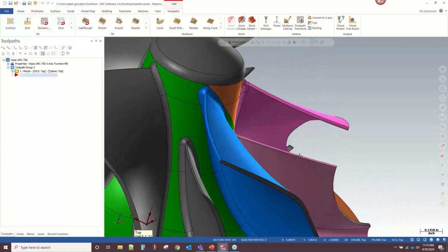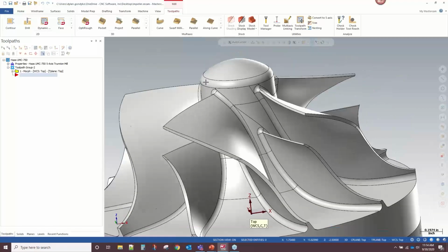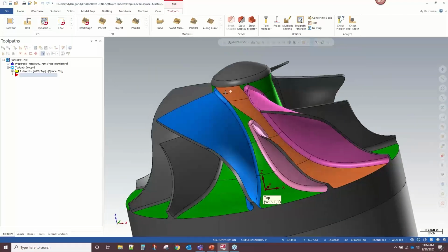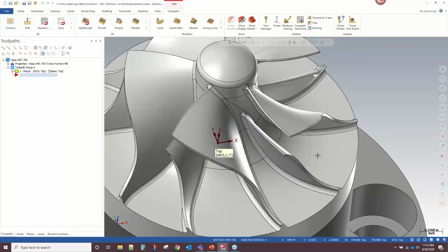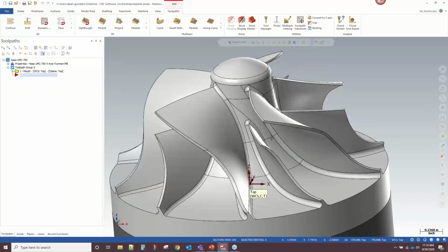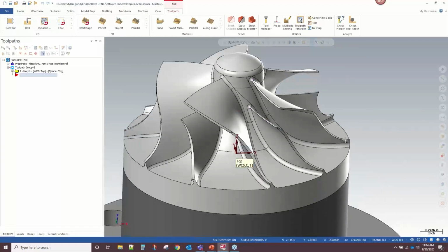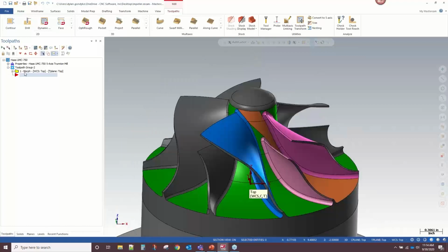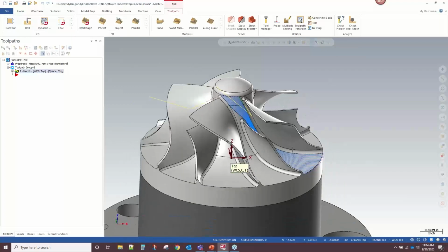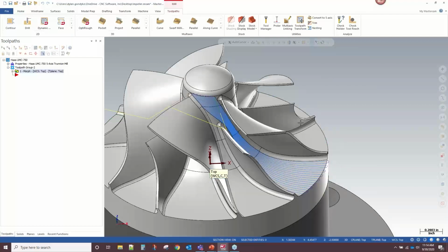And there's a really small gap in between the leading edge of the vanes. Things open up past the vanes up here, but we've got this choke point, and then we've got to follow that choke point down for some distance. So this is going to be something that isn't initially very evident what you would do to control this well. So I set up this morph, and I've purposely turned off collision control to start out with here.